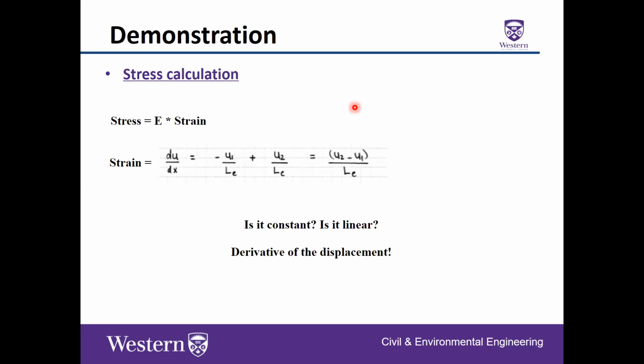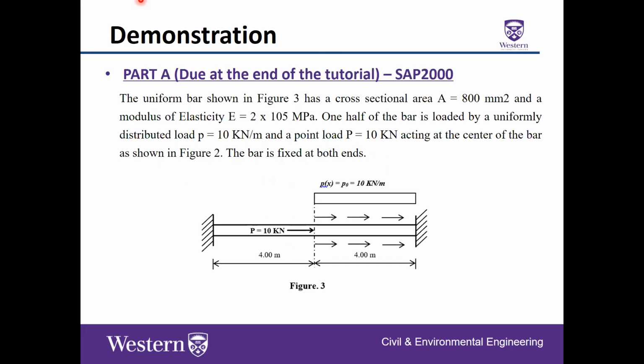So how do you solve the question that is usually asked by Dr. Ayman? When he asks about the stress, you look at the strain. And when you look at the strain, you're actually looking at the displacement function, because the strain is the derivative of the displacement. So again, pay attention to that, because you're going to use it in the assignment, in part A, and you're going to use it also in part B. Right, so that's all for the first question. Any questions so far before we move to the second problem?